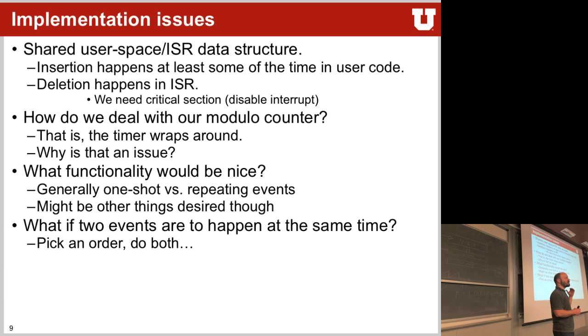So virtual timers are really nice because oftentimes you don't have limits in how many events you can schedule in them. At the same time, they're not as precise anymore as a compare register itself. So they're often good for stuff that has soft delays and soft latencies. If you need something at a very precise time, it's really difficult to do in a software virtualized system.